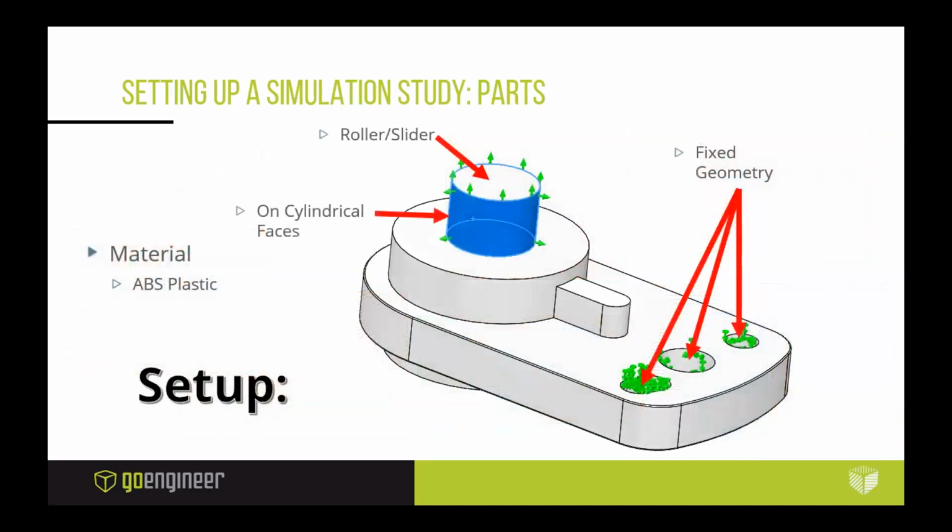So this is what I'm going to be doing. I'm going to run through a little example where I'm setting this guy up with some fixtures. I am assuming a static scenario where this maybe is instantaneously impacting. I'm getting a force, which is coming maybe from the servo, and maybe where those three little holes are, that's what it gets attached to on the actual head of the robot dog. So that's going to be my point where I'm going to be fixing the model.